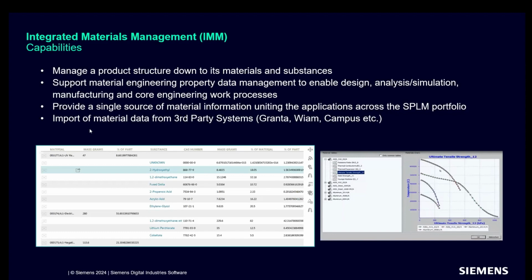Or let's say you've meshed two surfaces that don't exactly meet because of errors in the geometry translation, and when you zoom in, they don't share a common corner. We have tools that operate on that underlying geometry, where you can pick one edge and pick the other edge and say, align these together, with a lot of different options to do that. And the mesh will update.